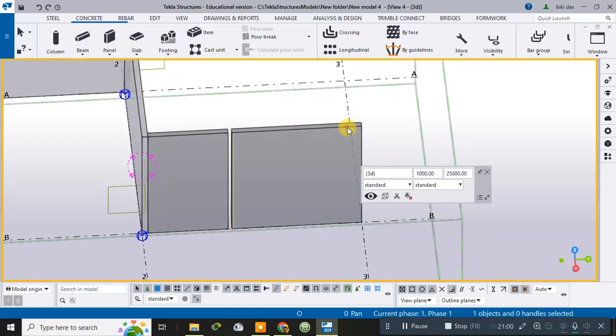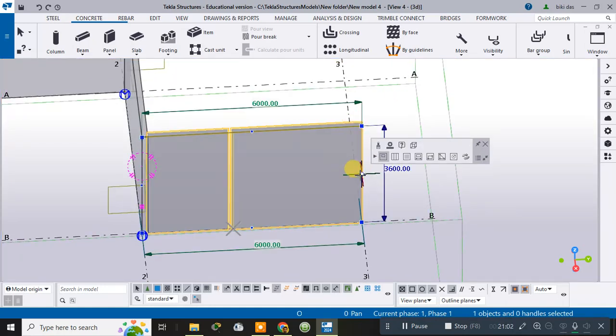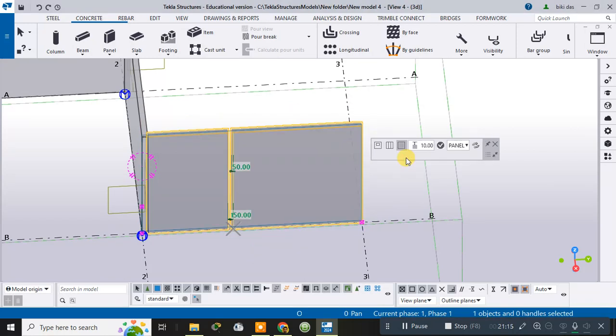After that, again click on the wall, again click here. After clicking here, now I have created the seams, or I can modify the seam. After that, modify the wall boundary offset. I can also modify the wall boundary offset. I will click here, and if I want to modify the wall boundary panel, suppose here 10 is present, I can increase each height. Suppose I make it 500 and I click it.